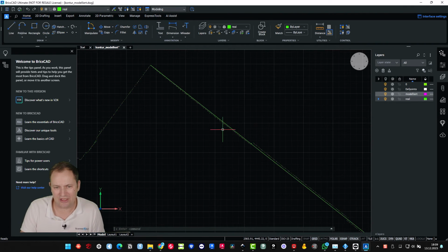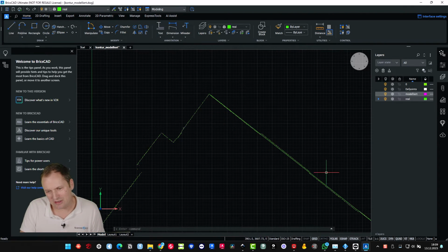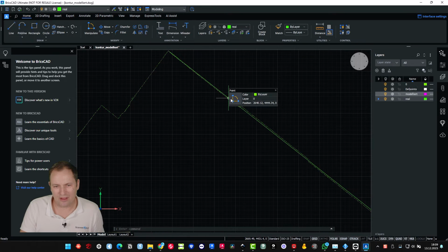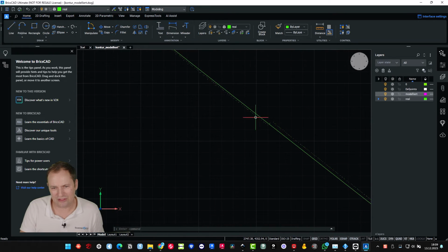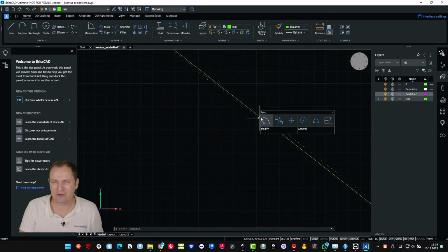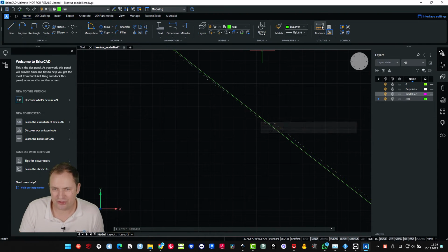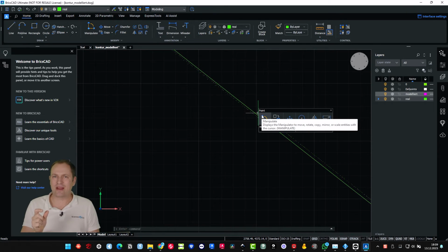And then you see here this deviation. You see this wall is even a lot better to demonstrate the point of this tutorial. What I'd like to explain is, first of all, you see here's a deviation from the points to the line you have drawn. Use the measure tool to measure the distance from the point to the line to get an understanding of how far you are off the line.